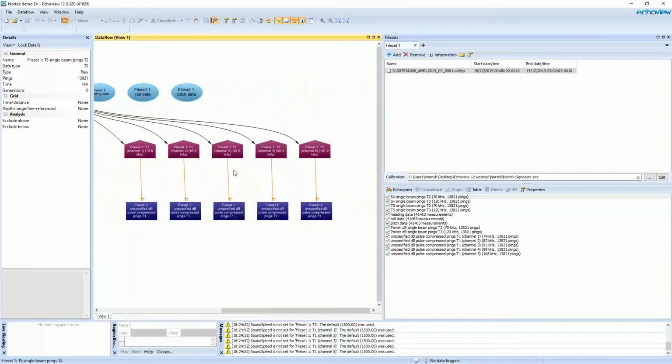And the same system can also collect wideband data. We don't yet read the wideband data as the original chirp or complex data, but we do read Nortek's pulse compressed variables. So this is wideband data that's had a bandpass filter applied across 5 frequency ranges, and we provide that pulse compressed data. So there's no wideband complex information behind this, it's just the pulse compressed values.